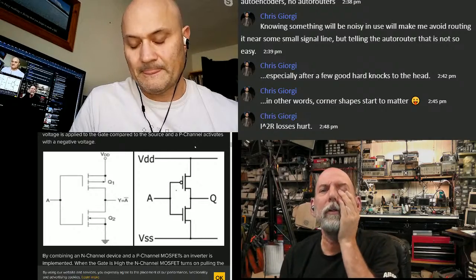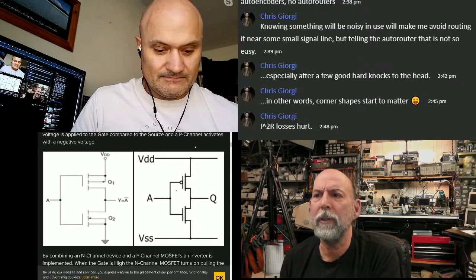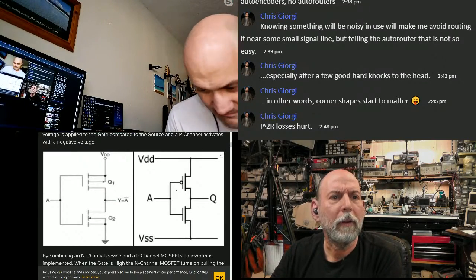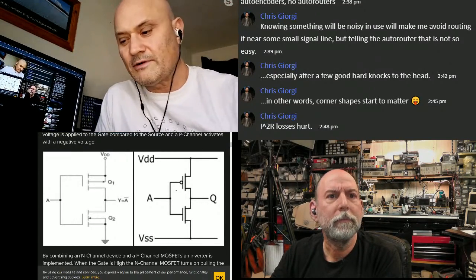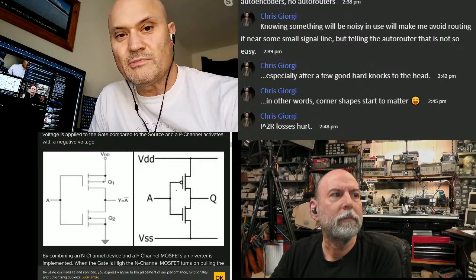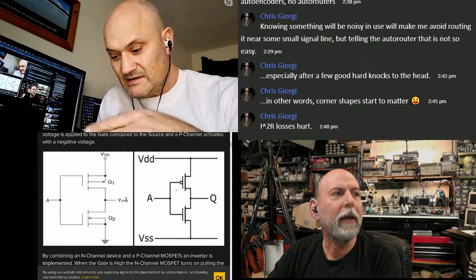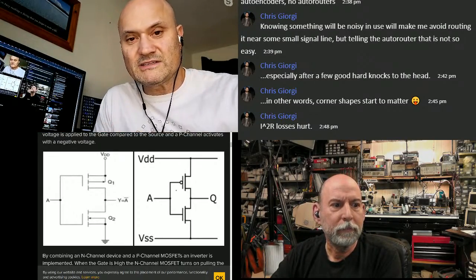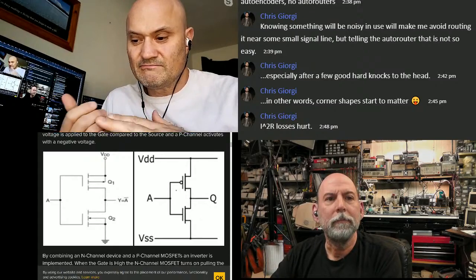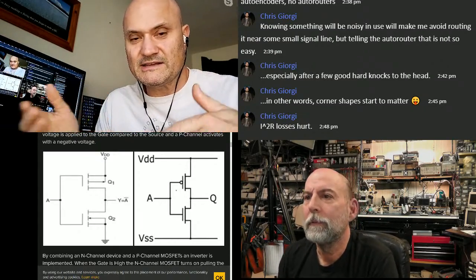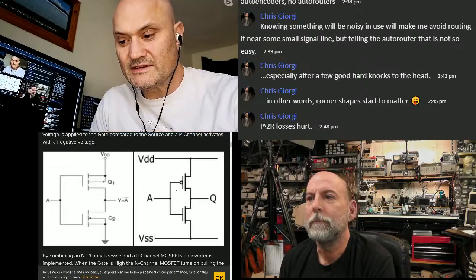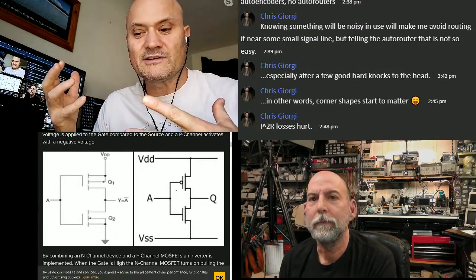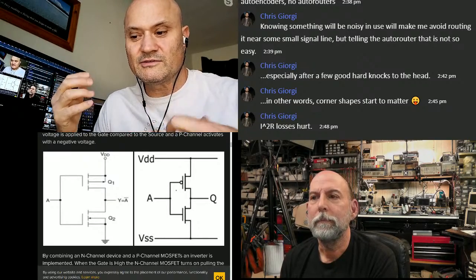Oh, you looked into that a lot, didn't you? Didn't you come up with a way? Yeah, I know technically it doesn't seem like a hard problem. It's just a mechanical CNC machine with a polishing wheel that only polishes over your high-speed traces in between laminations, and would mirror that polish on the adjacent plane layers. So your return paths can be good as well, and then everywhere else you have the black oxide or the brown oxide on the copper to get good adhesion.